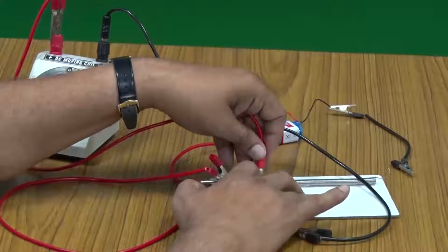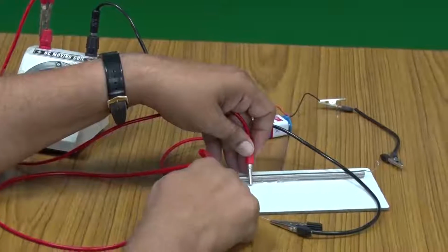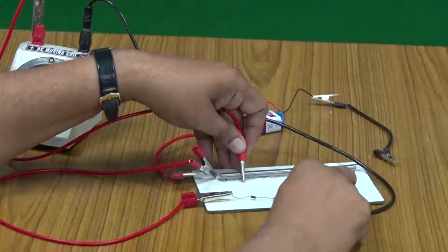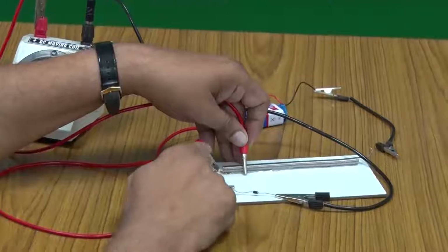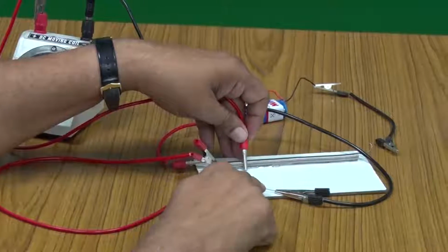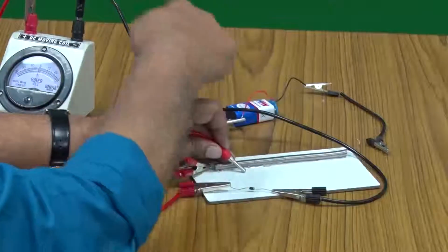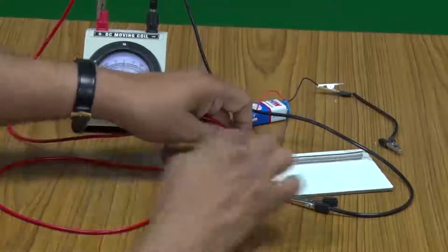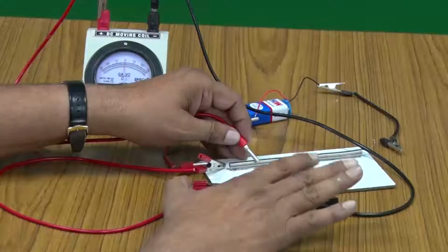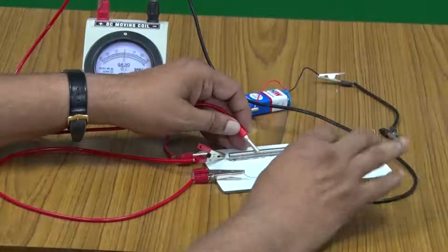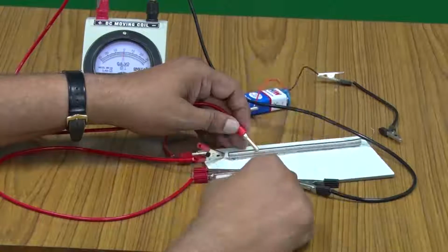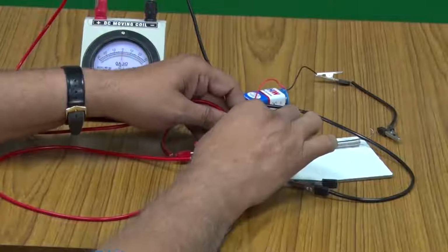So, suppose this is that potential source here, and then from the positive side I am connecting it to the P side of this diode. This is the P side without silver band. So, from the positive of this potential I am connecting it to the P side, and then the N side is going to the galvanometer, and then back from the galvanometer to this lower potential side. So, this is a forward bias situation, okay, and the potential that I am giving to this diode, of course the resistances etc. are there, will be just this much, whatever potential is on this.